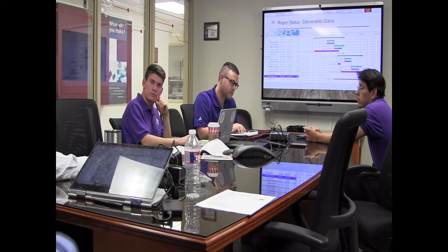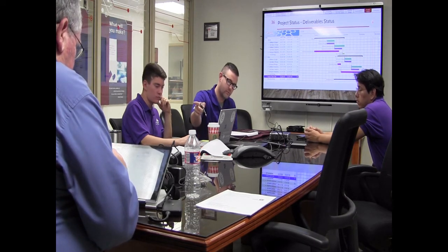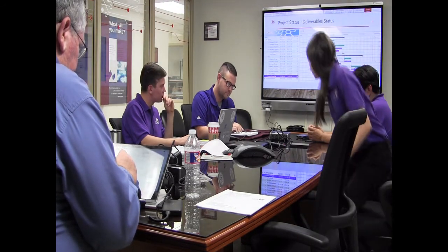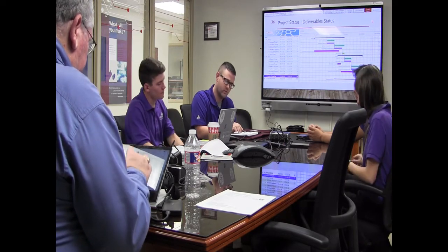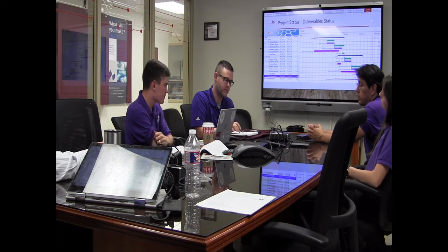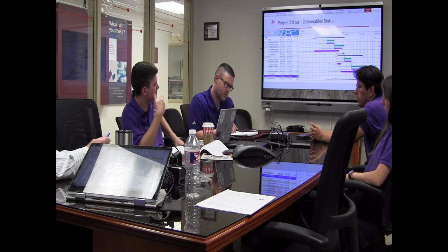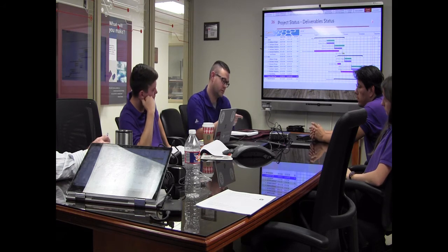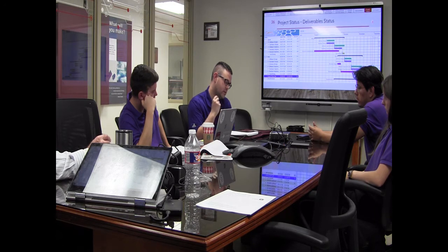So anything else? The additional 4 boards, exactly. Let's see, so action items were guarantee motion detection. We're going to look into power monitoring just after this. We're going to look into how possible it would be to read register values from the PCA9685. We plan on doing output voltage selection videos and a how-to series for how to actually operate these boards. There needs to be a note on the low side switches that for inductive loads, back EMF protection is needed. Need to do a final power check on the 12 volt H bridges for voltage drop issues on our beta board. Look into adding new projects in Cayenne. Yeah, that's big. Credentials and alternate credentials for Google.